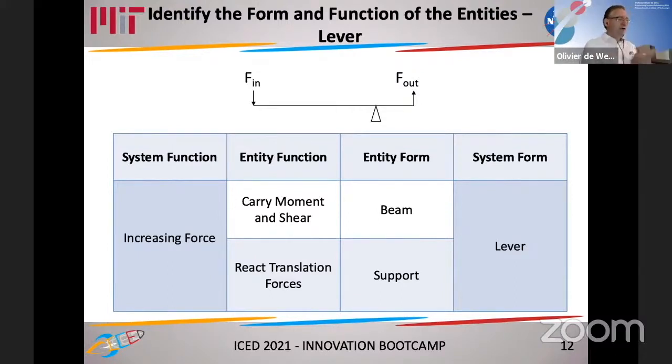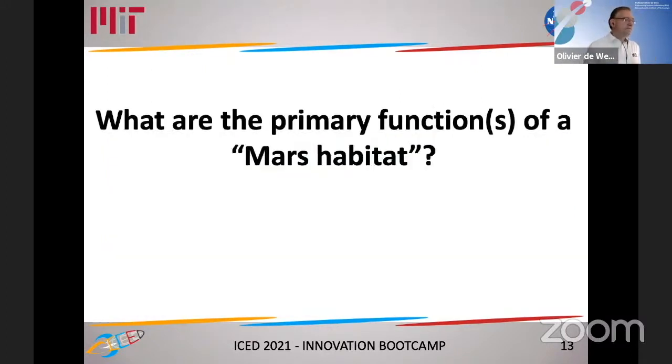So coming back to our example of the lever, you can now see that the beam is essentially there to carry moment and also shear forces, of course. And then the support is there to react the forces into the base, into the ground. And so you'll have the reaction forces that create an equilibrium, force equilibrium.